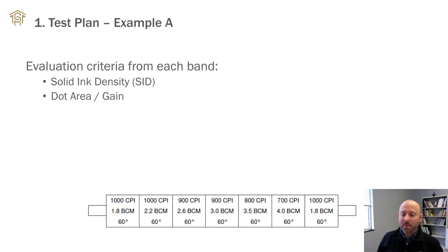And that might be something that kind of eliminates. So if we have a whole lot, we can cut it back, but if we're getting a whole lot, there's probably a problem there. So another thing to keep in mind with a banded Anilox or a trial like this is you want to see failure. Failure tells you that things have gone too far, and you want to see failure at both ends of the spectrum. And what you really want to do is, all right, it's failing at this end, it's failing at this end. Where is it in between? Where is it good? You can tell, success is always in the middle of failure.